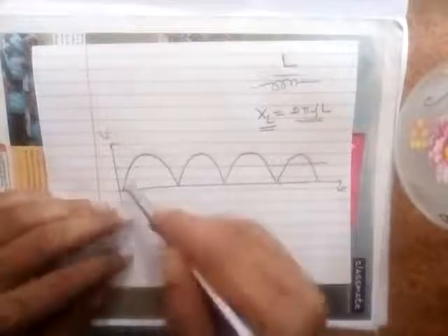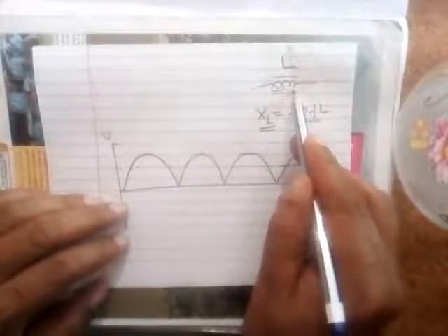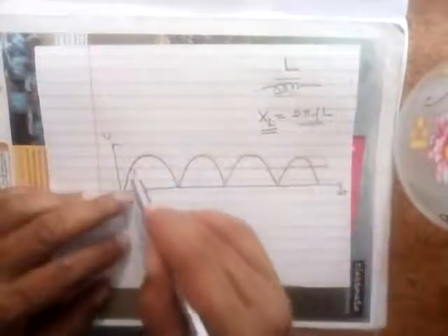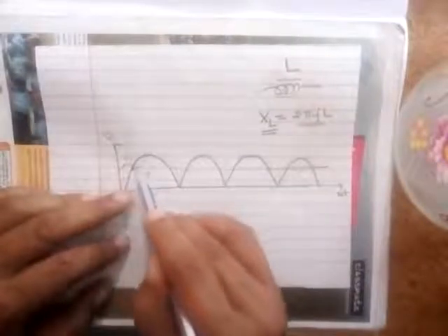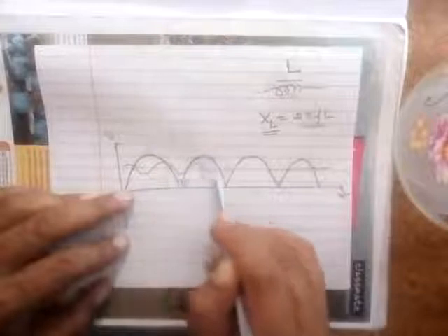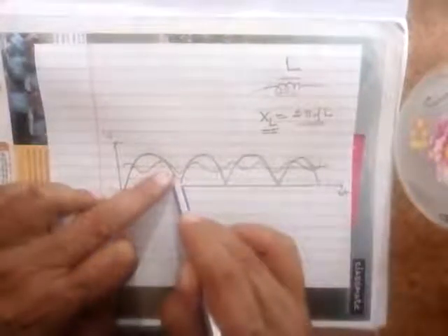Now what happens is that when this current reaches a certain value, or the average value, the energy is stored in this inductor. This stored energy opposes this sudden change here, and you get the output something like this. It won't let it fall beyond this level. So this is how an inductor works, along with the principle which I told you yesterday.